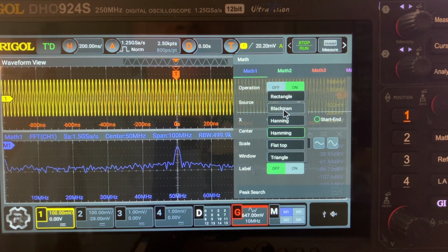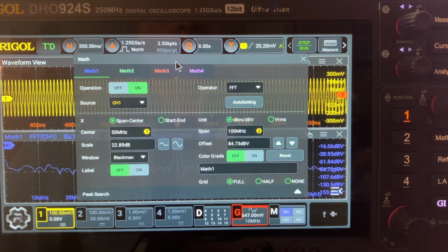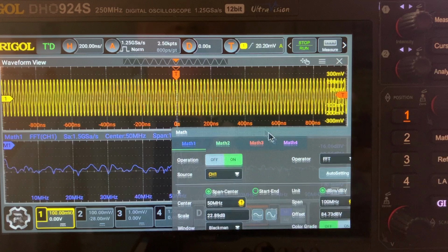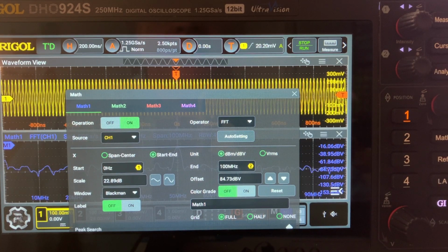But if you want to look at the signal to noise, you're better with Blackman because the signal to noise gets lower. You don't have much definition on the position of the peak, but you get everything related to analysis if there is a peak. I see here at 0 frequency there is something. So let's work with that one because we want to know what's happening with frequency. The other thing we need, let's put start and end.